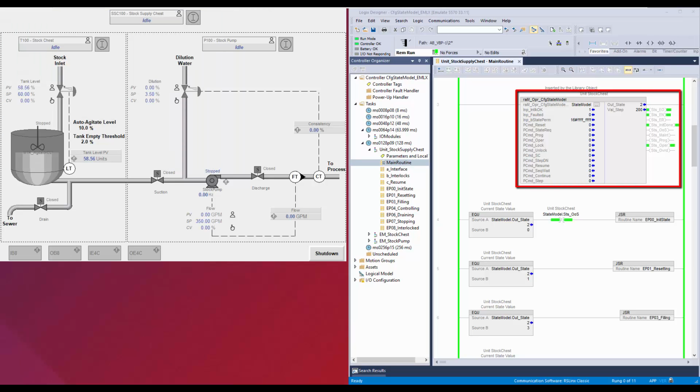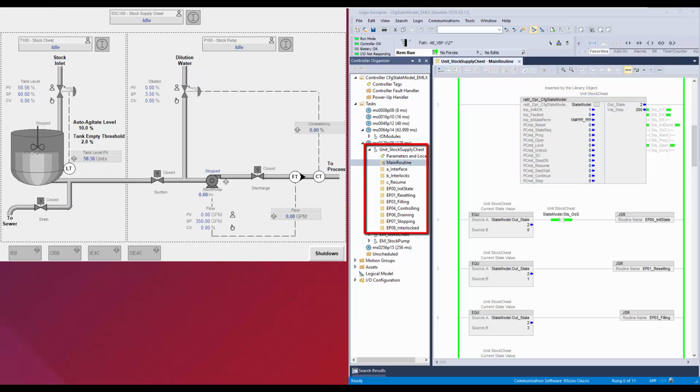The configurable state model instruction provides a flexible control mechanism where the states and their transitions can be configured to build an application framework. The user will only need to program the action logic for each state. This helps in faster and easy application development. The state transition relations can be configured from HMI or using Logix Designer without any code modification. This allows easy customization of application.